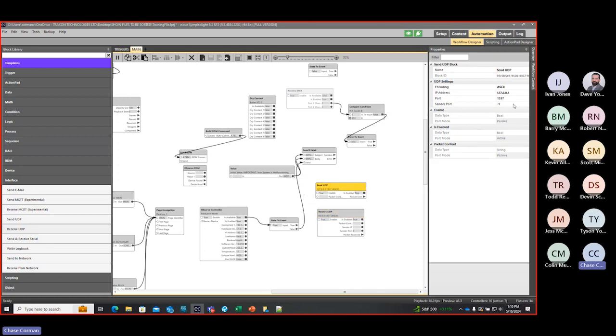So that's very helpful. Obviously, we're going to set the specific IP address that we're going to send to, and the specific port itself. This can change. Depending on the complexity of the other system you're integrating with, they may have problems changing what their UDP or even their RS-232 or RS-485 string may be. They may have very, very specific, very rigid requirements for what they can send and also what they can receive.